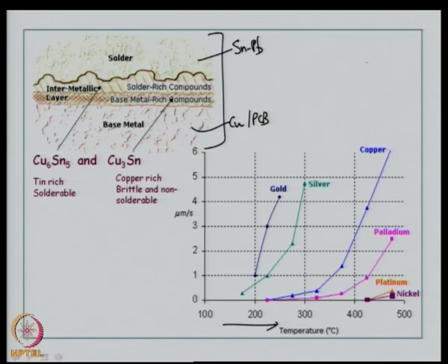We have also seen in our earlier class that when you want to plate gold on copper, you need to have an undercoat of nickel to prevent diffusion of gold into copper. So, the intermetallic properties are dependent on the alloying system, the plating, the base metal, and the multiple coatings that we normally do with printed circuit board cross sections.